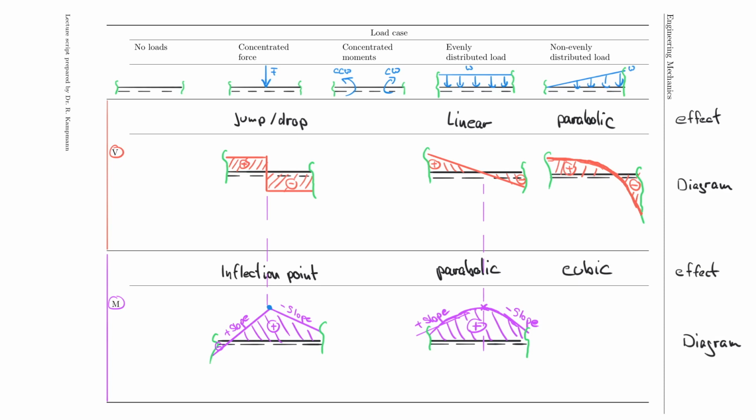All right, and of course now there's a relationship to the bending moment that is the same as always, which is where it's 0, we need to find a maximum, and we need to have a cubic function. So let's draw that cubic function, at least conceptually.